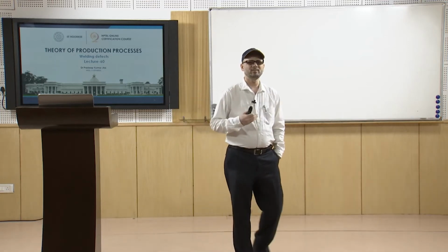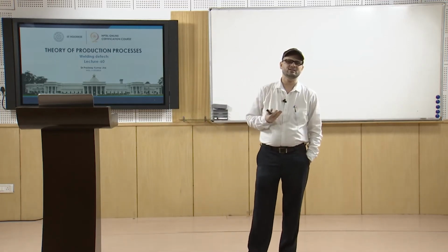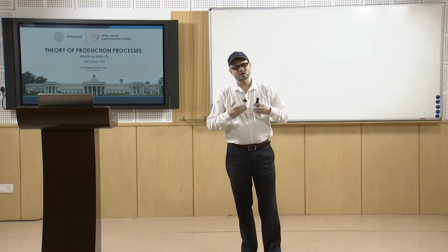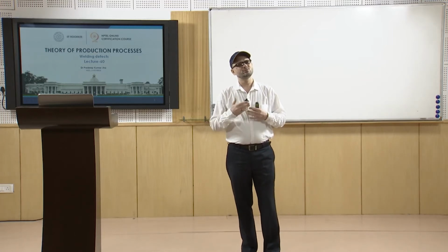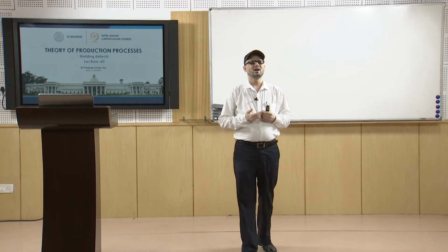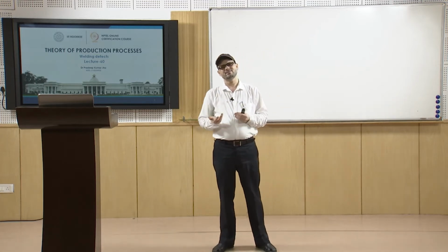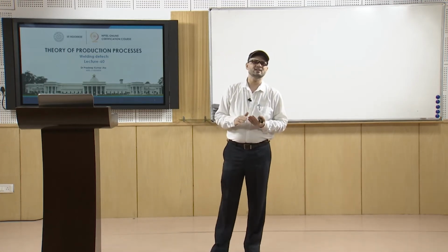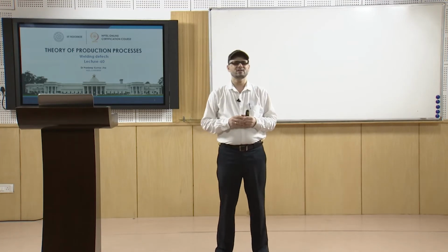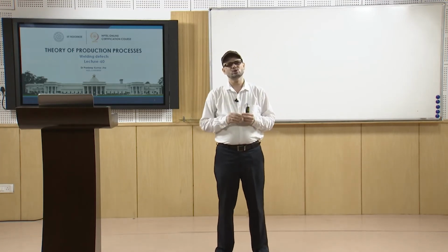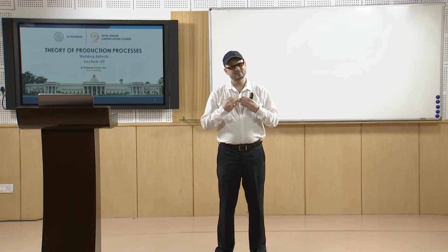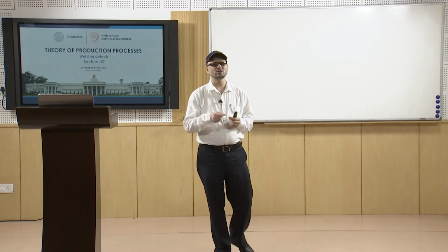Now, what is a welding defect? The quality which we expect, if we do not get that quality, then we say that there is a defect. Like if we do not get the proper weld surface or proper weld contour, or there are cracks developed, or even the formation of stresses, or inclusions.